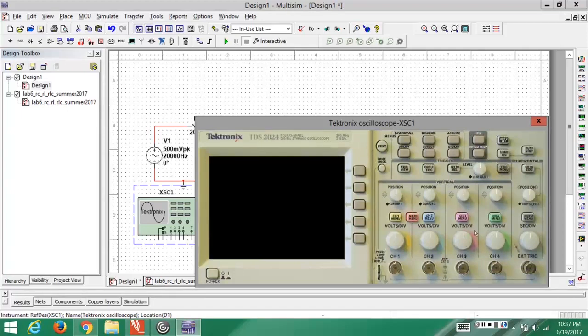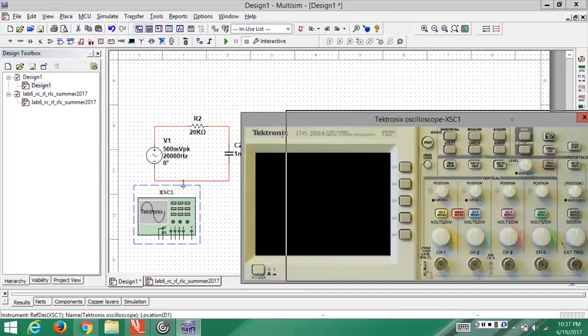The simplest thing to try is, once you set up your oscilloscope with the probe and connect it to your circuit, and you know that you're receiving some sort of signal or reading in your oscilloscope, we try this auto set button over here. That calibrates the oscilloscope by itself and shows you whatever waveform it is picking up, and we get to measure the voltage or the time on the x-axis from that waveform on this black screen. So I'll keep it on the side.